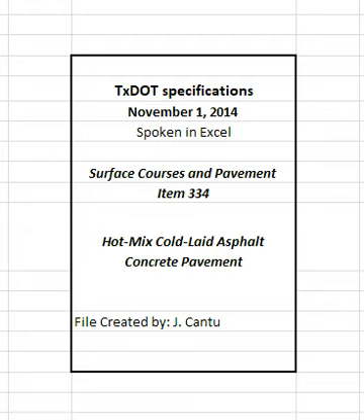4.2.5 Moisture content. Furnish the mixture at a moisture content of no more than 1% by weight when discharged from the mixer, unless otherwise shown on the plans or approved. Cease operations at moisture contents above 1% until corrective actions reduce moisture content. 4.3 Hauling operations. Clean all truck beds before use to ensure mixture is not contaminated. Use a release agent on the department's MPL to coat truck beds when a release agent is necessary.